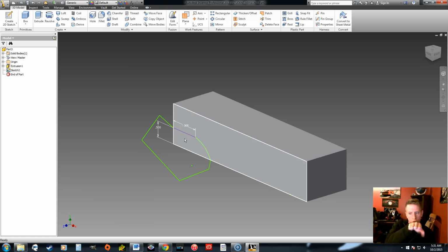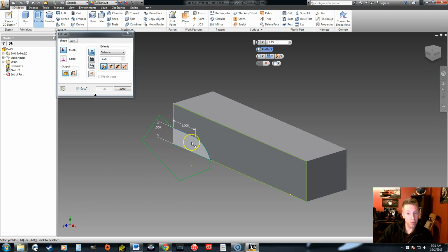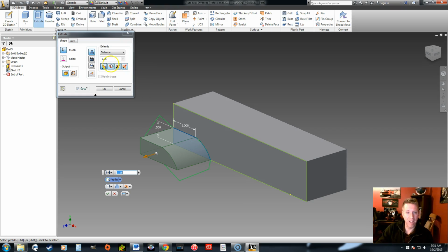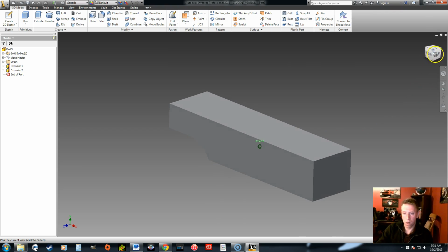That shape is going to go whoosh in. It's going to cut away on the Z axis. So I'm going to extrude this new shape that I just made. I'm going to extrude it as a cut. Notice I can click cut. I click OK, and I can choose the depth of my cut. It's going to go all the way through. There you go. Bam. All right.